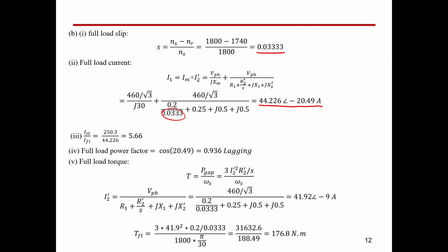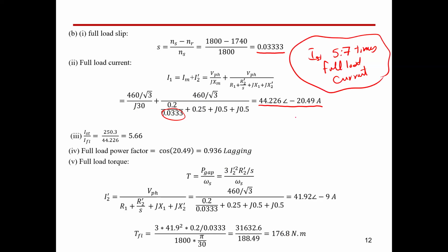It's more than 5 times. And we mentioned that starting current is going to be 5 to 7 times the full load current. And this is what we have here. Okay, so this makes sense according to our theoretical studies or our basics of the induction motor.